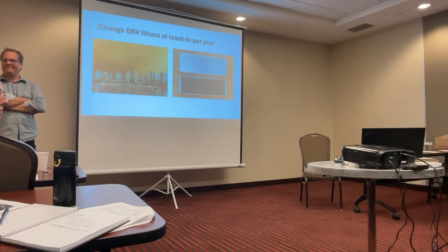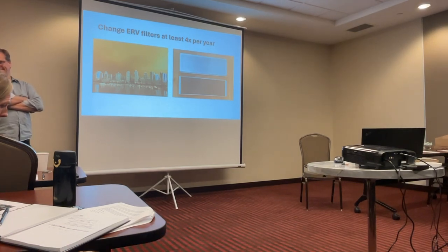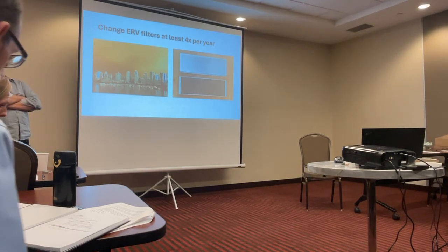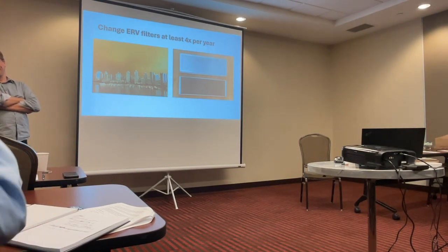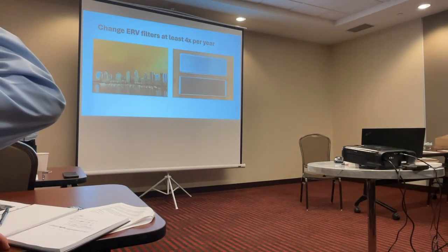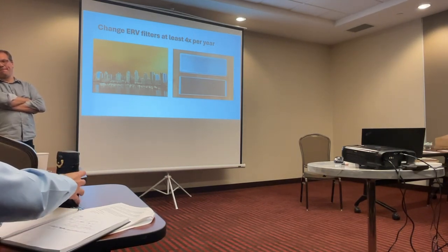And I'm just thinking, the size of these filters is not fit for purpose for the condition they're in. So as we start seeing these things, and the manufacturers want to hear our experiences too, hey, can we have a bigger filter that we only change twice a year? That'd save me so much money. It's easy for you to build in. And always have that feedback with the manufacturer's side as well, as we move forward.